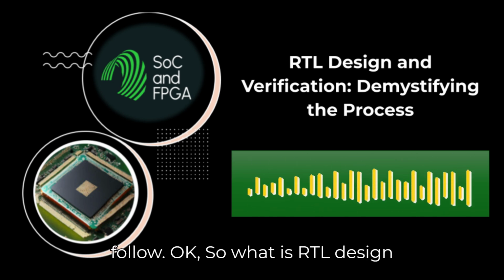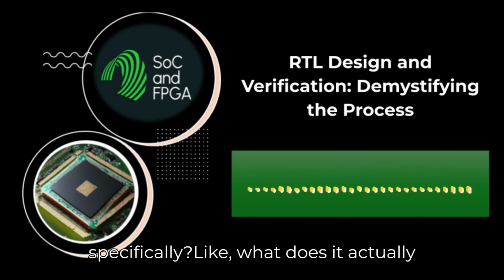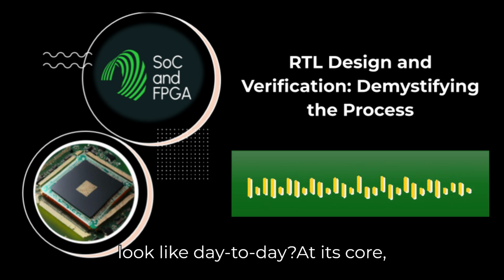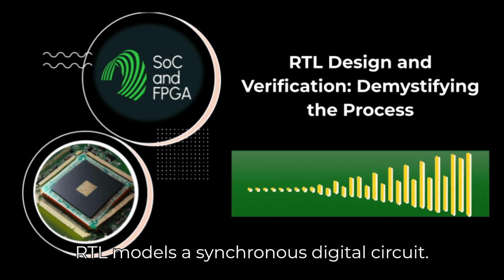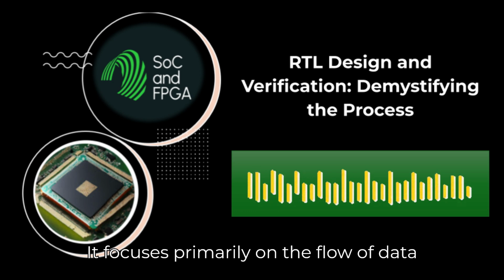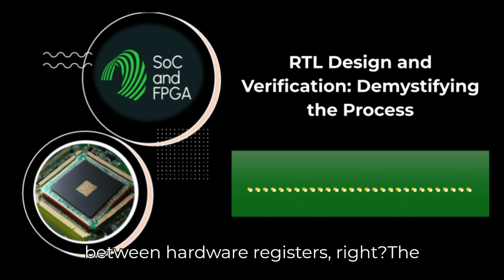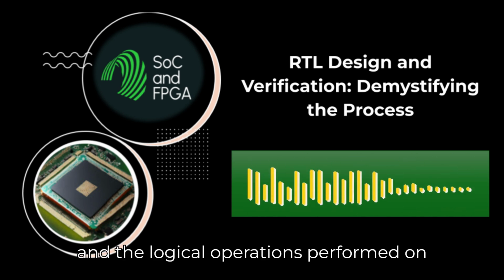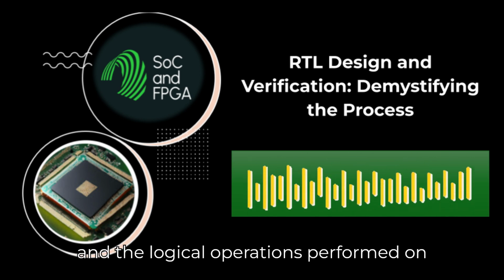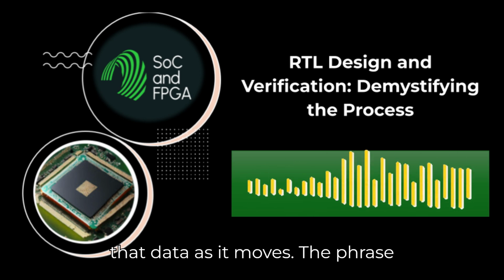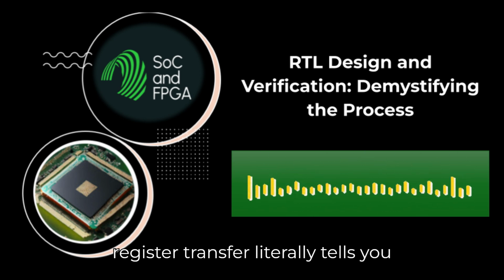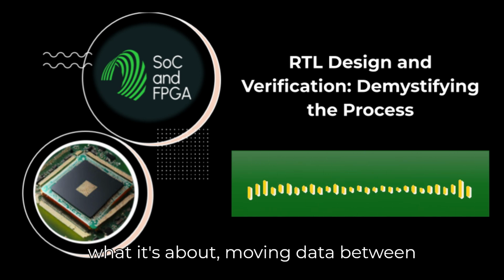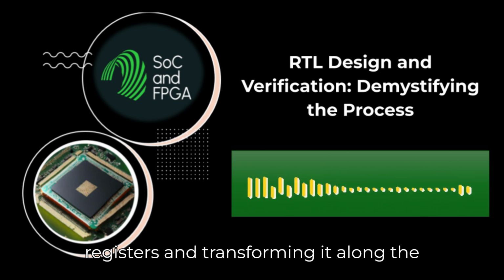Okay, so what is RTL design specifically? Like, what does it actually look like day to day? At its core, RTL models a synchronous digital circuit. It focuses primarily on the flow of data between hardware registers. Right, the storage spots. Exactly, the storage spots. And the logical operations performed on that data as it moves. The phrase register transfer literally tells you what it's about: moving data between registers and transforming it along the way.